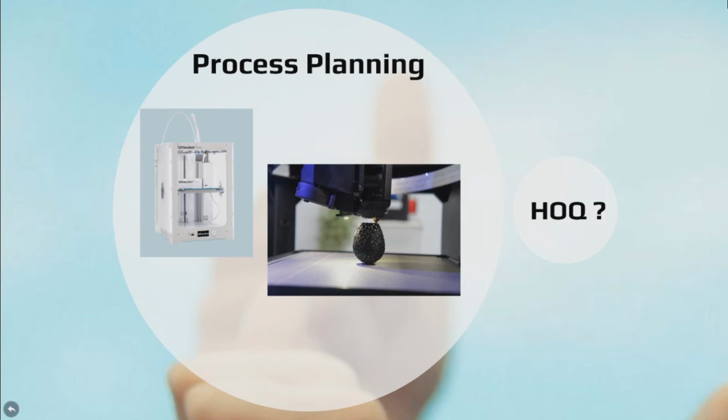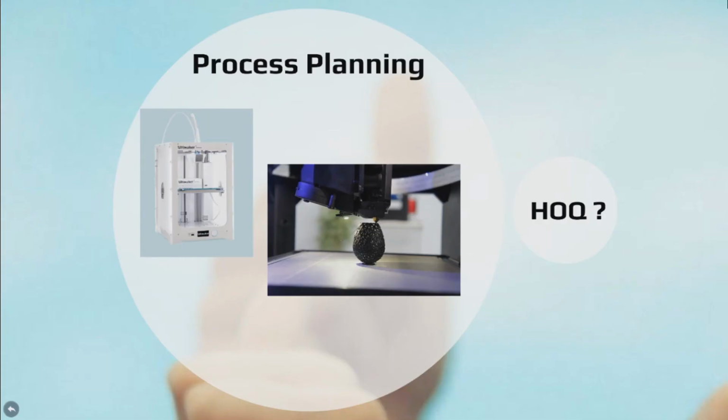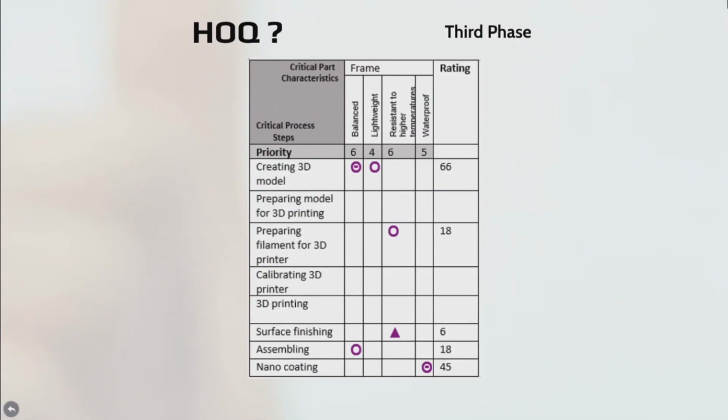That is why we choose Ultimaker 3 Plus extended version with pretty high set build volume. So, our process steps are separated in a few stages. First of them represent creating 3D model in 3D modeling softwares like SolidWorks, CATIA, etc. And after that, exporting to readable format called STL. I say readable because of our next step called preparing model for 3D printing.